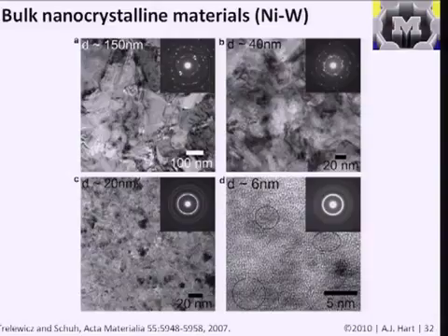Basically, you have a bulk material, a piece of metal, and if you zoom in with a microscope, you're going to see it's all these little connected pieces. And when we talk about defects and dislocations, we talk about the motion of the individual pieces of material with respect to one another before you've applied enough load to actually break the individual bonds. And it's possible using processing techniques for a lot of materials to manipulate the average grain size.